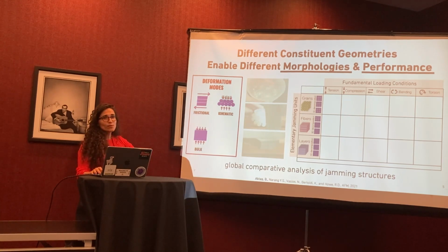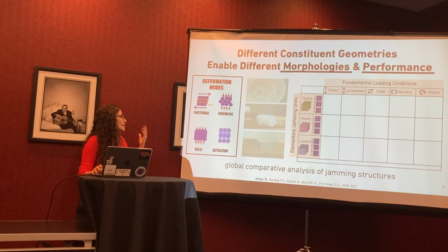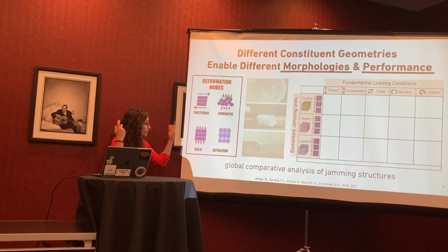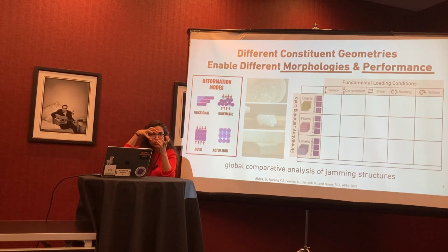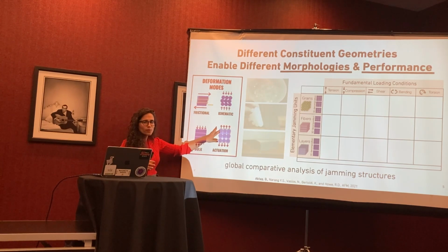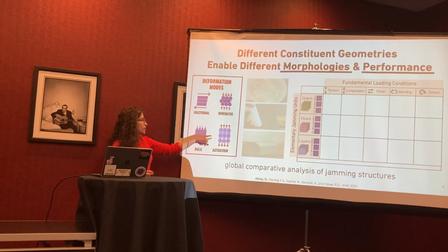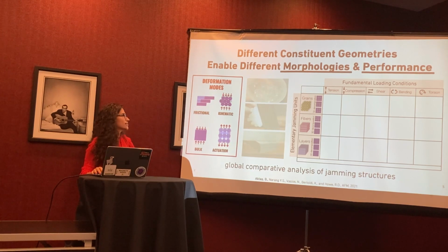The third and most boring one, you're just squishing something onto itself, so the jamming doesn't have an influence, doesn't do anything, but we have to cover it. And then lastly, actuation. So you're opening this, you're stretching things apart. So in the vacuum actuated case, what happens is the bag wants to compress because there's a vacuum applied. So the shape of what you have inside doesn't matter so much. It's basically the actuation method. And here, the deformation is mostly elastic, so it goes back to its original state.